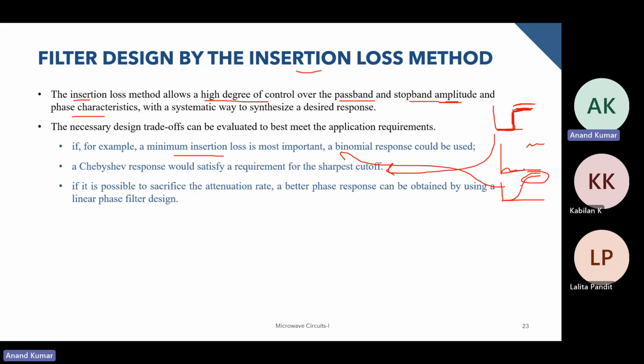So for example, if you have a low pass filter, it will be maximally flat, as we also call it. It will be very flat over here, very close to whatever signal you're transferring, and it will go through. But the roll off between the passband and the stop band will be very slow; there is no very sharp cutoff over here.